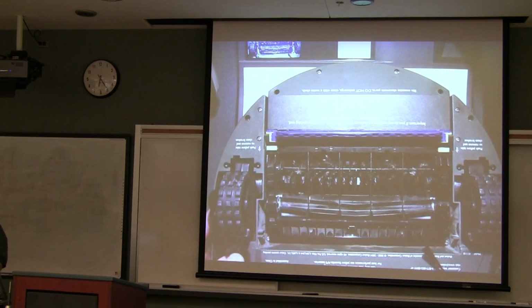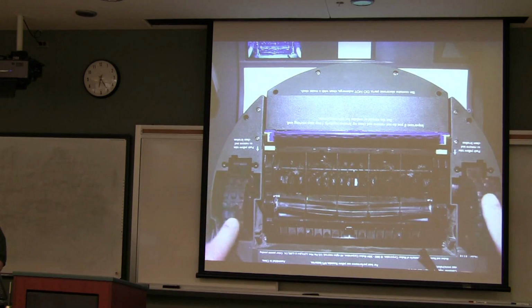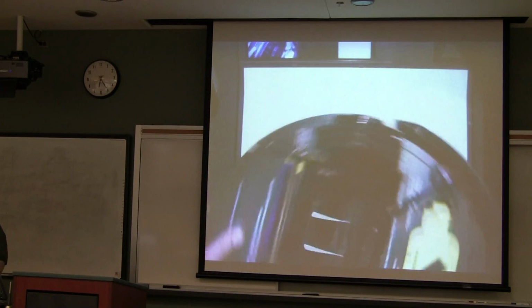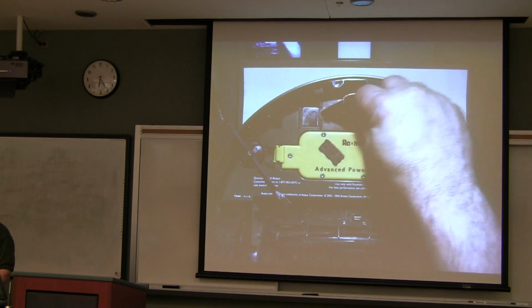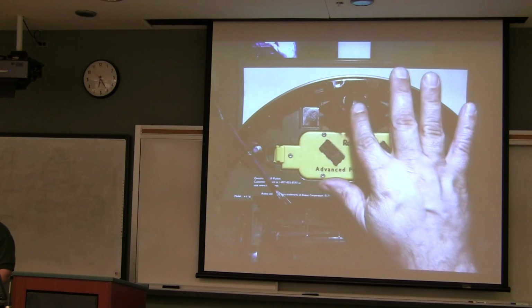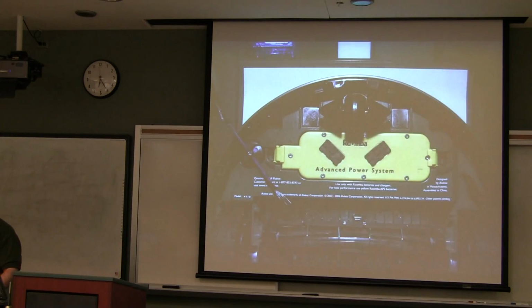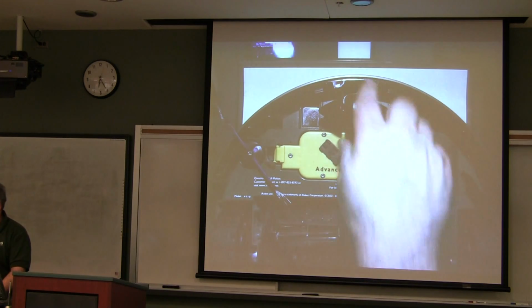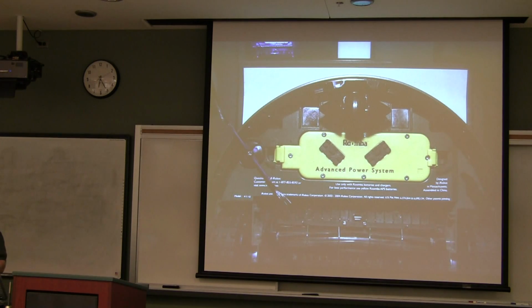All right, so we have down here the bottom of the Roomba, which has wheels. If you look at this carefully, this has interesting shock absorbers. But the other wheel here, and these are the only two wheels that move, but they also have something that is, oh, look at that, it doesn't turn or anything like that, right? So it'll go forward and it also absorbs, but notice it doesn't have any Swedish wheel type of thing up here. And when they went to a new version, they actually put on a caster wheel that would actually move in different directions. But what other actuators do we have here? Motor.